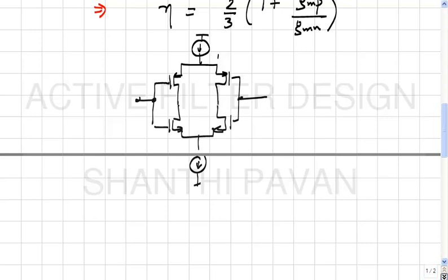Okay, but where do you think you will apply the common mode feedback? There are two ways of doing it. You can either make this current source dependent on this, or vice versa. We can go through the same arguments that we did and the same circuits. Anyway, it turns out this has other practical problems, but in principle, this is a transconductor with an excess noise factor of only 2/3.